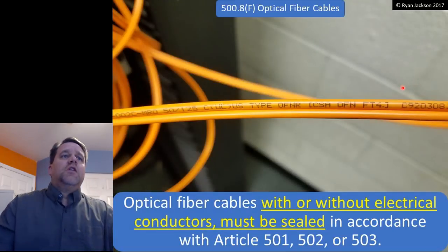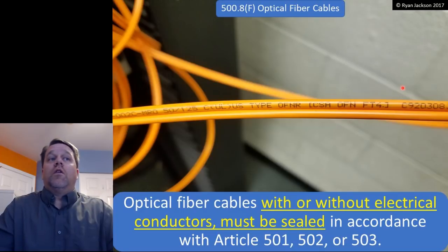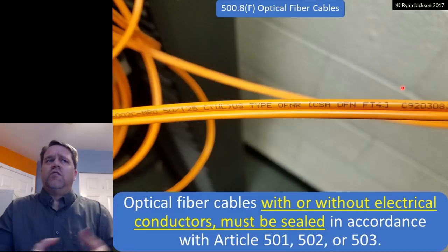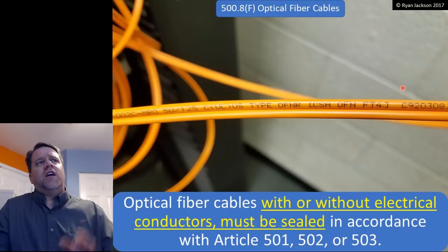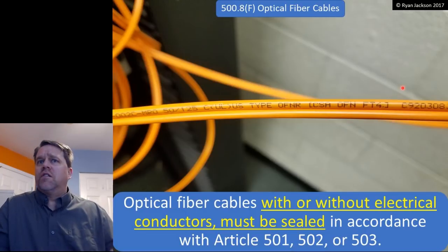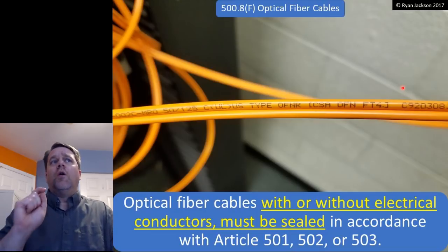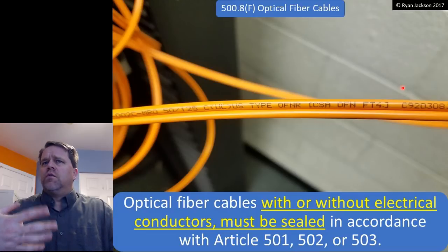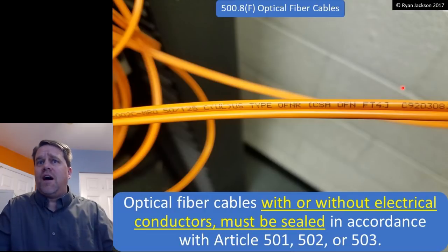Optical fiber cables, with or without electrical conductors, have to be sealed in accordance with Articles 501, 502, or 503. We're not going to cover that tonight because we're not going to get into Articles 501, 502, or 503. But suffice it to say, optical fiber cables are not electrical. So why do I need to concern myself with that? Well, you can still transmit gases through openings around an optical fiber cable. So if we were getting into the sealing rules, it would make sense, but I'm not going to cover all of Chapter 5, at least not for free.